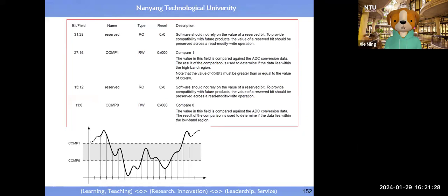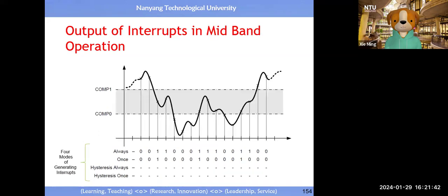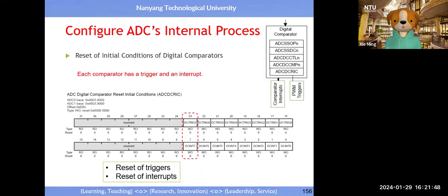When it goes beyond the upper limit or goes beyond the lower limit, it triggers an alarm, right? And how to trigger the alarm, you can also tell the system whether to always trigger the alarm or just trigger once. Then you follow this explanation, right? Even when going below the low limit, how to trigger the alarm, etc. It's very powerful, right?